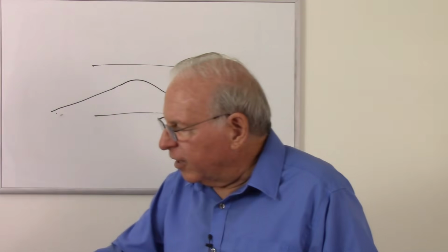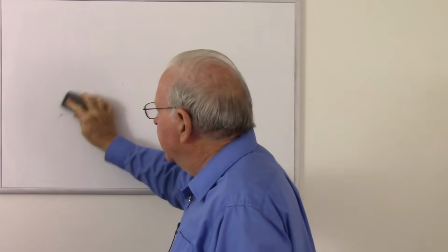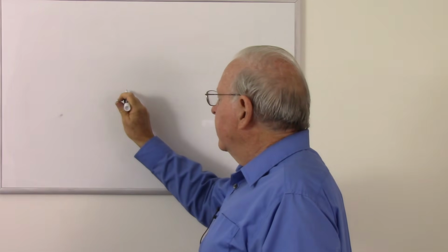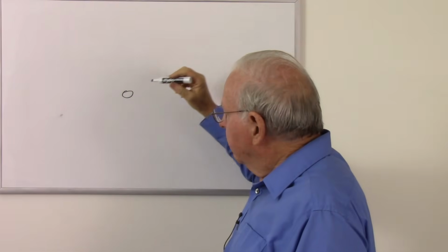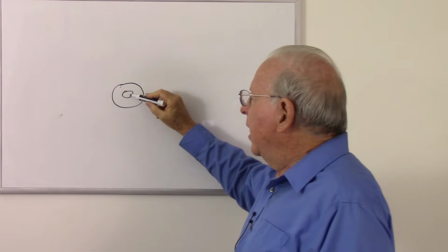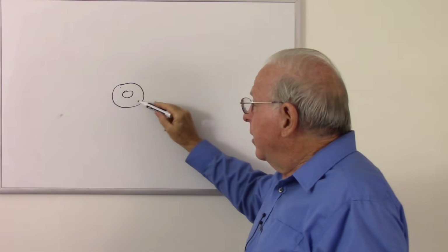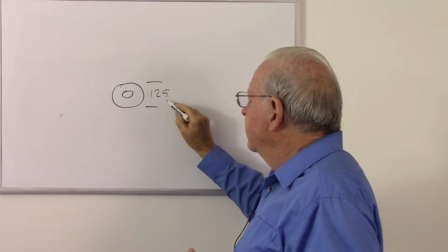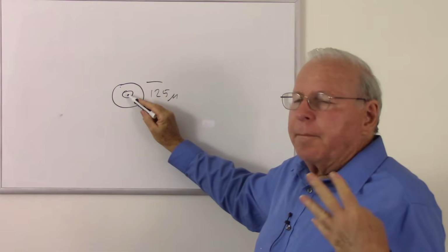Okay, so that's the basic idea of what is going on in the fiber. Let's look at some cable construction for a moment because we'll be looking at that down the road. So real quickly, we already said that our fiber is going to have a core. That's going to be the graded index, step index, or multi-mode, single mode, whatever. There's going to be a cladding around that. Your typical core size in single mode fiber is 8 or 9 microns. Your cladding is typically 125 microns regardless of the core. So 8 microns for single mode, bigger for multi-mode.